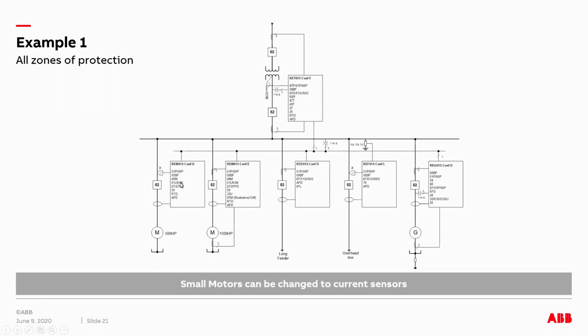And as you have noted, for the feeder, the configuration is changed to configuration L, because that is the configuration which accepts a current and voltage sensor input. So we change the configuration of the relay depending on the type of analog input it receives.